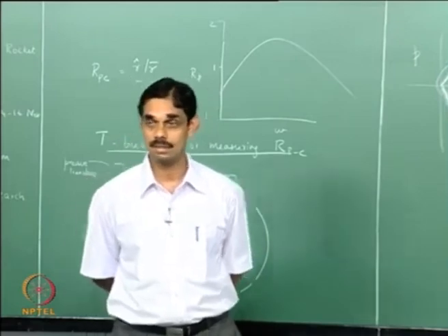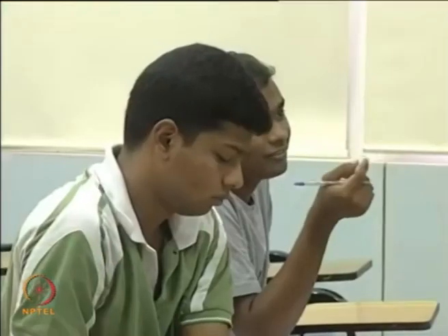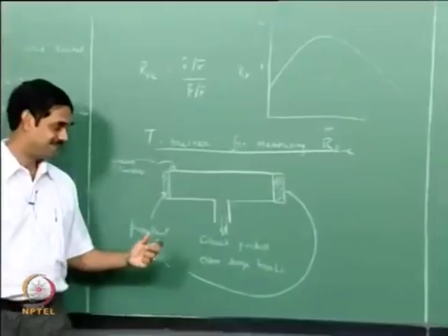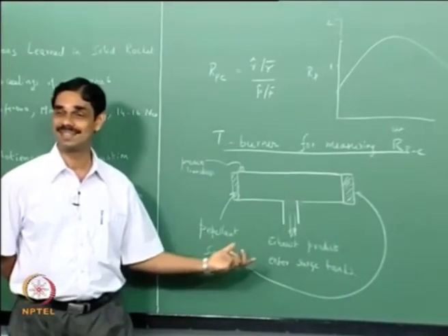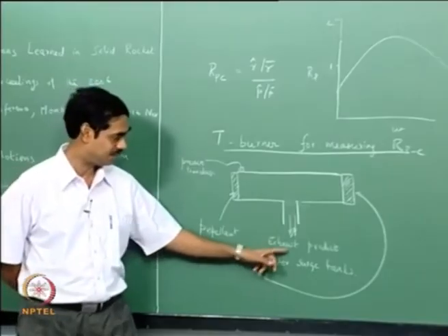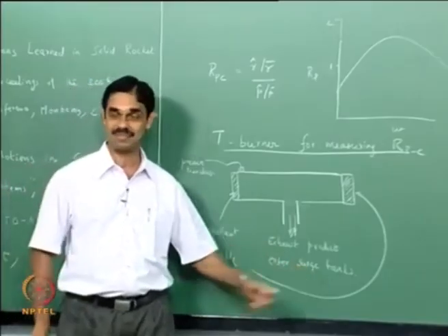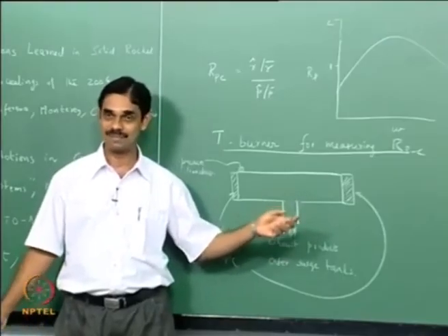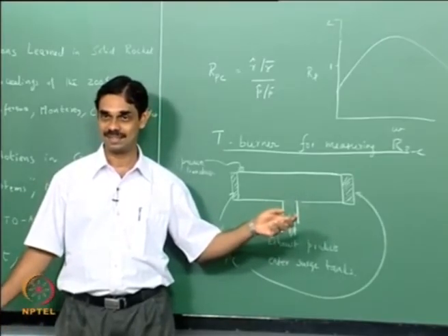Any other questions? Beginning increase in the mean pressure will be there, no? Yeah, beautiful, we have to connect this to a surge tank, so that's why I said exhaust products enter a surge tank, which has a very big volume compared to this volume, so that pressure won't change much.